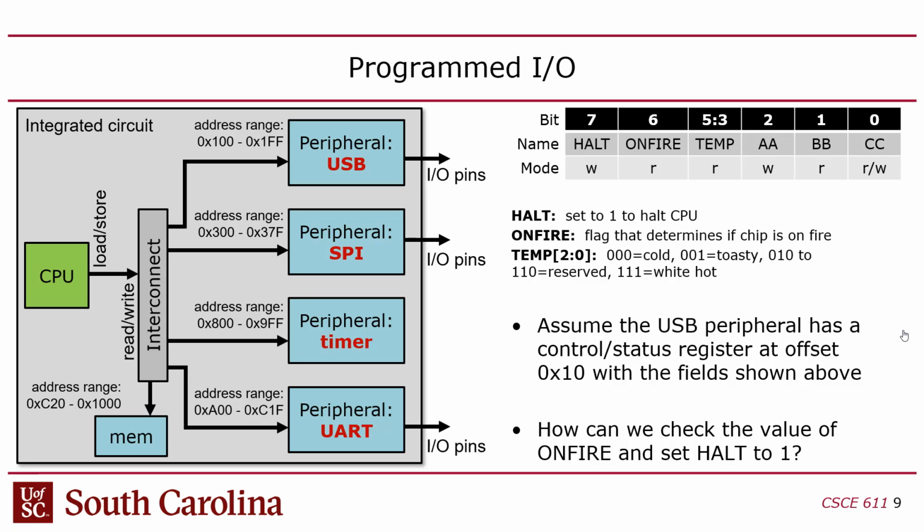I mean, unless you were writing a simulator for, say, RISC-V. Think about it. If you wanted to simulate a RISC-V processor, you would have to go into each instruction and take out the different fields, right? If you wanted to disassemble an instruction, you have to go in and grab fields and figure out what each bit field is. Well, it's the same thing here. When you interact with the hardware, you have to extract bit fields and set bit fields.